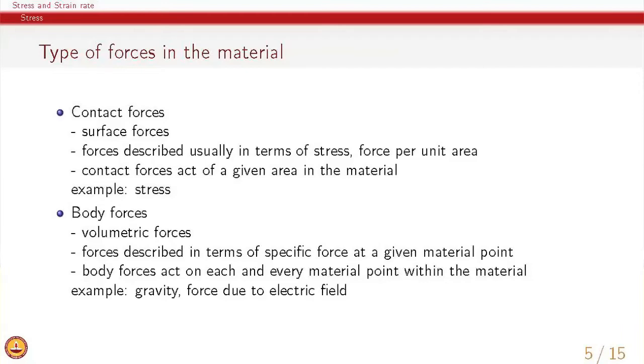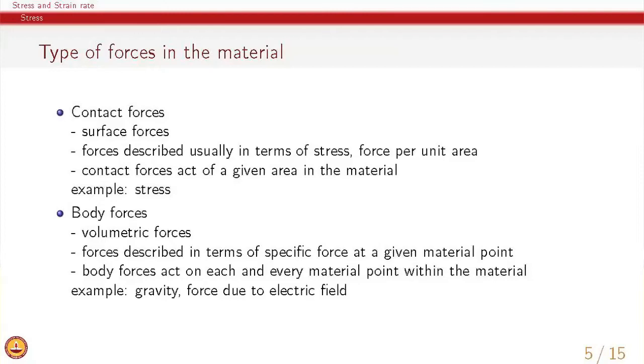So, all of these again are felt throughout the material wherever there are charges or wherever there is mass. Given that continuum is composed of material points, and each and every material point has a density, therefore, each and every material point will have gravity. Similarly, in the continuum picture, whenever we have a charge, the charge will be distributed on each and every material point, and therefore, each and every material point will feel a force, and we know from physics that the force will be the charge times the electric field. So, therefore, the body force can be felt at each and every material point.